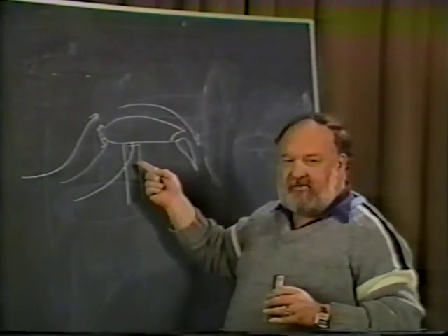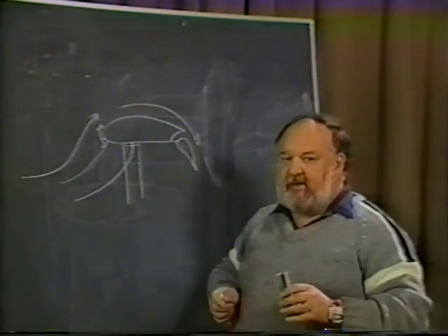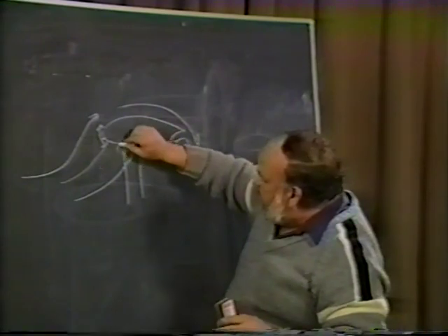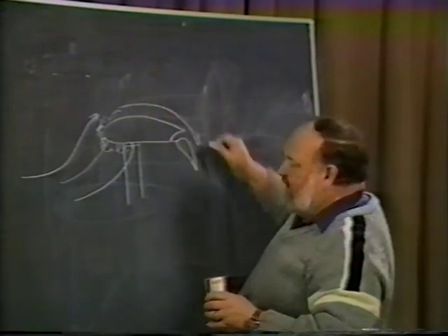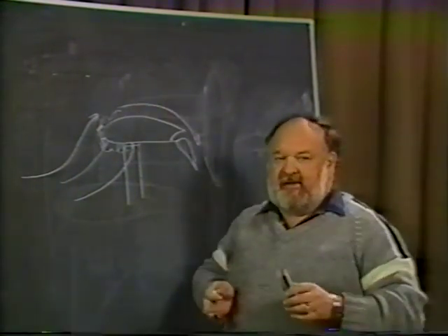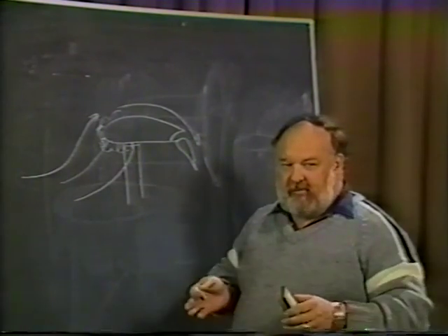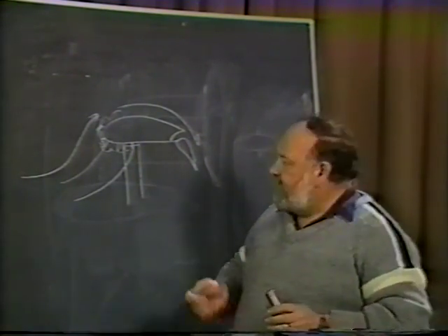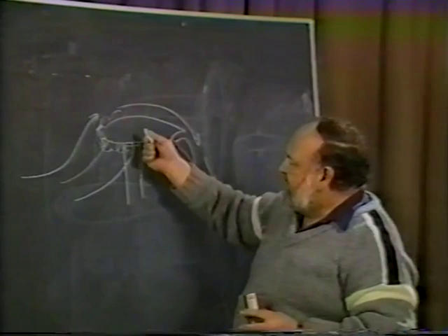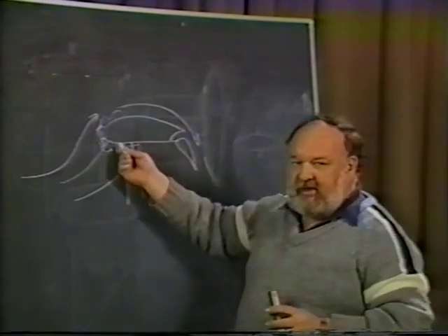But as soon as it got to the strut area, in that one region where the strut met the wing, it actually would separate here and cause turbulence and cause the wing to start stalling in that section of the planform where the strut would meet the bottom of the wing. So when you're working on this type of stuff and doing design, be careful what you have down underneath there.